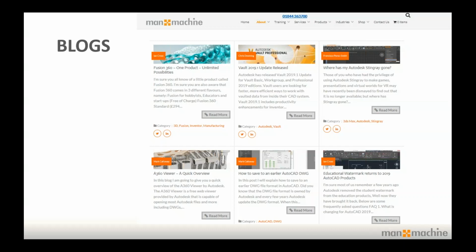But you're getting premature failure, and it might be a result of two things. You might get vibration from the truck motor, which is inducing vibration in the frame, causing fatigue, and happens to coincide with the natural frequency of that structure. Or alternatively, you might have stiffening of the welds, in which case you get a stress concentrator at the welds, and this is very, very common for welded structures.